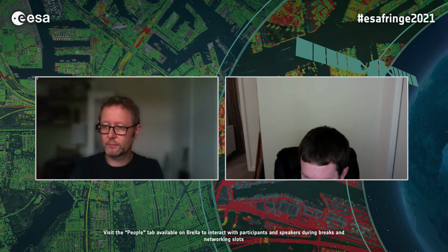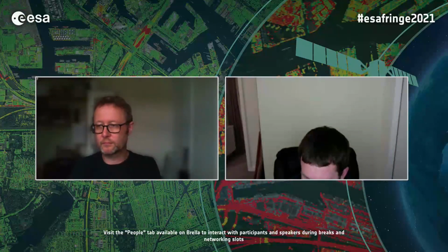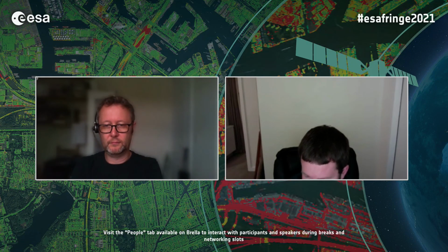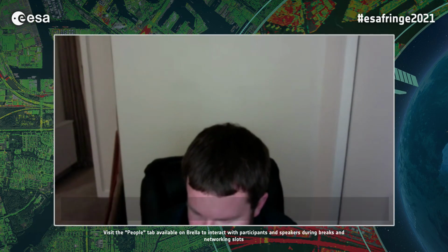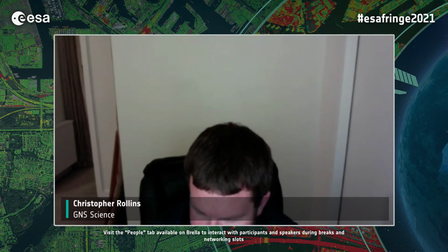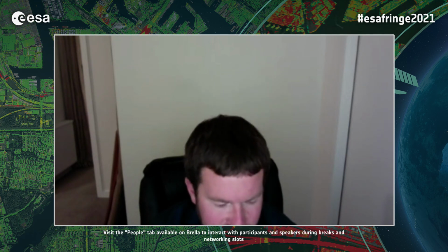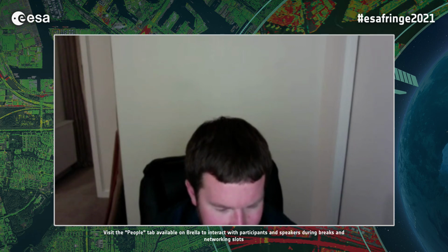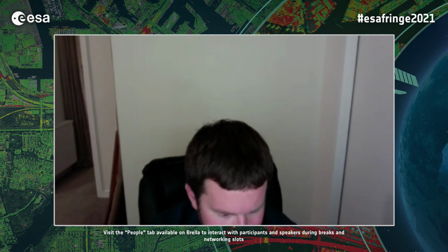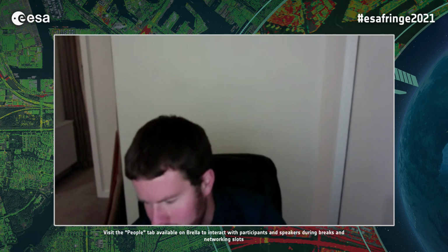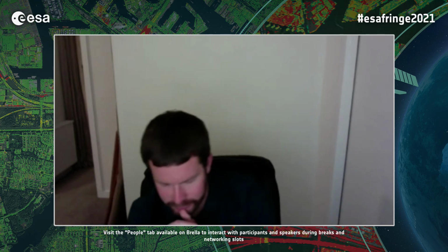So the only smoothing or averaging we did is the multi-looking that Milan did, just uniformly across the entire thing. So there wasn't anything in particular done at tectonic boundaries. I don't think there were extra problems with tying to GNSS across a boundary, though I can understand why you would really want to make sure that the GNSS are right. So we may want to go back and maybe quality control the GNSS across the NAF in particular, or just make sure that the InSAR is going right through it in profile. So that's a good idea.